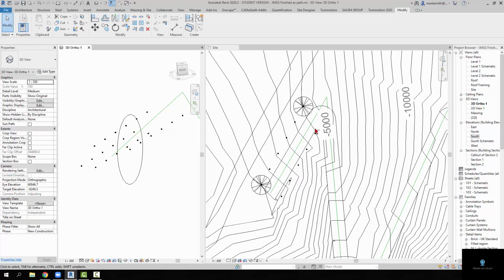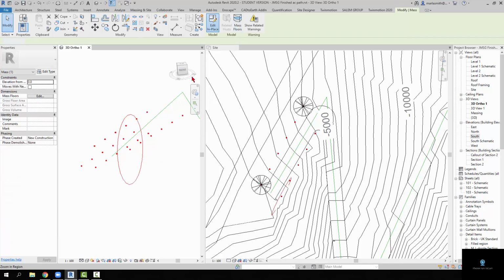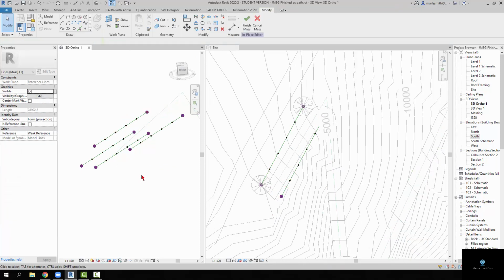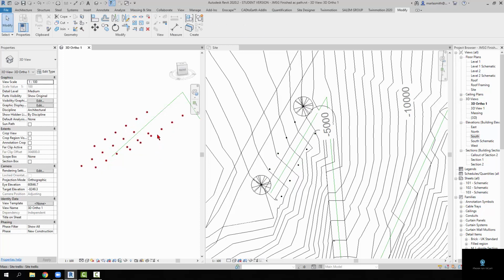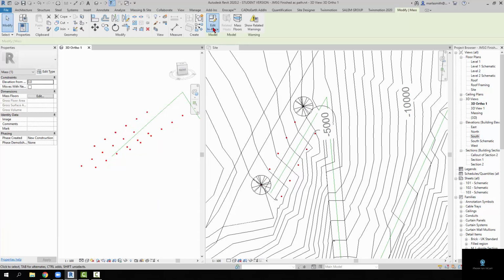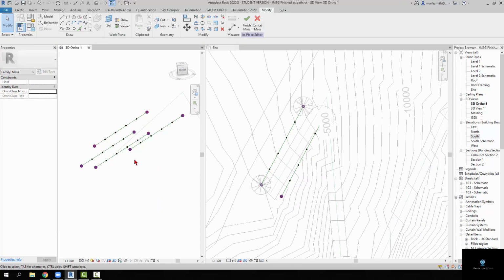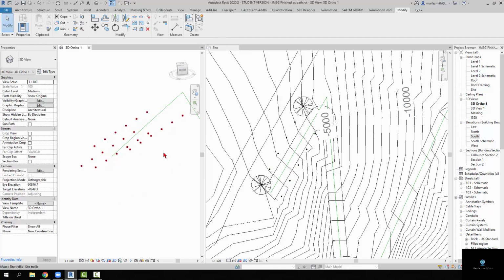well, you can see the points, which is enough too, but now you can actually select it and get back in, so I don't really need that circle. So let's finish. But you need to have something that you can pick to edit in place to get back in there to see those reference lines. So if you don't have divisions on it, you only have reference lines, you're going to need to put a model line in there to do that. Okay. All right, when we get back, I'll put a component on there.